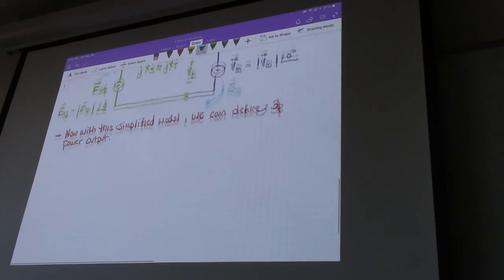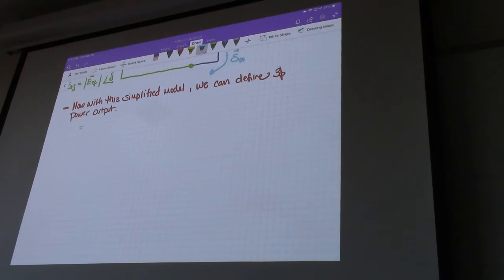Okay. So, we'll start with the most basic definition and then we'll keep building upon it. The most basic definition of S infinite bus is S equals V I conjugate, right? That's the starting point. So S will be equal to V infinite bus with an angle of 0 degrees times the conjugate of IA. As you can imagine, the 0 degrees is going to go away, because it'll be added to whatever the angle of IA is.